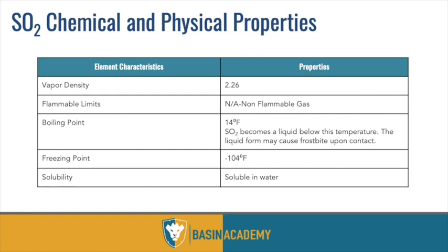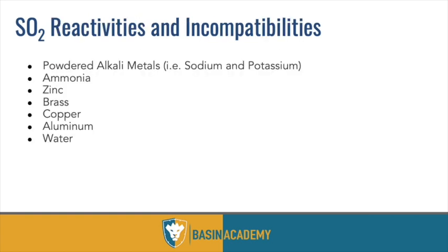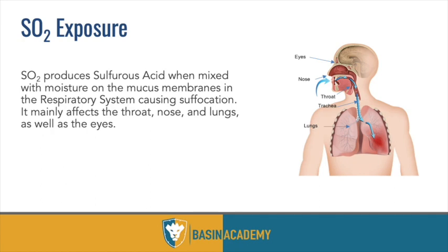So, SO2 exposure compared to H2S exposure, again, your body only has so many ways of telling you something's wrong, so it's going to be similar. You're going to experience suffocation, irritation of the lungs, irritation in the nose, throat, and mouth, dizziness, headaches, nausea, vomiting. All these things are another way that your body tells you, hey, I have a foreign contaminant in me, and it's not good, so I'm letting you know.